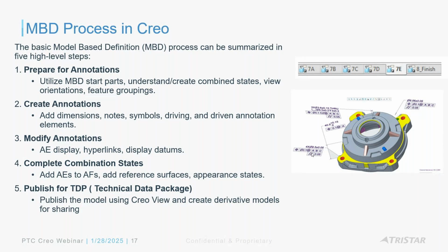It could be your Creo View lightweight viewable, which you're already doing with your windshield configuration with the CAD worker, or it could be a 3D PDF, or maybe the new STEP AP242 format that can also have this PMI exported along when you do an export to AP242, including the semantic references there. So there's a process for that.